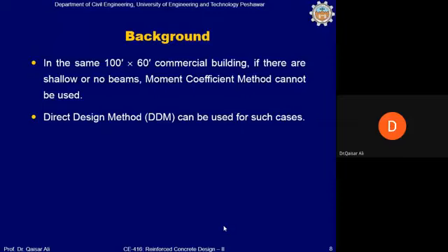However, if the situation is such that slab without beams are required, and if it is a demand from the client, then we would like to have the slab without beams in our system, especially if the structures are located in zone 2A and 2B. So this is the background of this system, and finally it will depend on many parameters. The final selection will be done after a lot of trials as to which system is to be finally used.